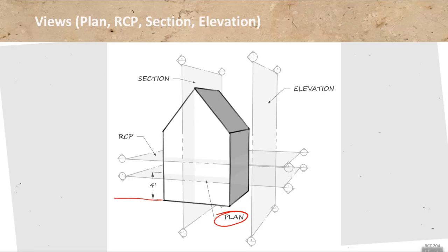So if my level here is there on the ground, then 4 feet up, that's where my first floor plan view is located. Then whatever that cuts through, walls and permanently installed items and so on and so forth, that will be represented on a floor plan. And anything that you can look at when you're looking down at the floor, so very often even floor patterns will be represented there, although sometimes they're omitted because it makes it just too busy to look at. There are sometimes things above a floor plan cut plane, and those need to be included somewhere.